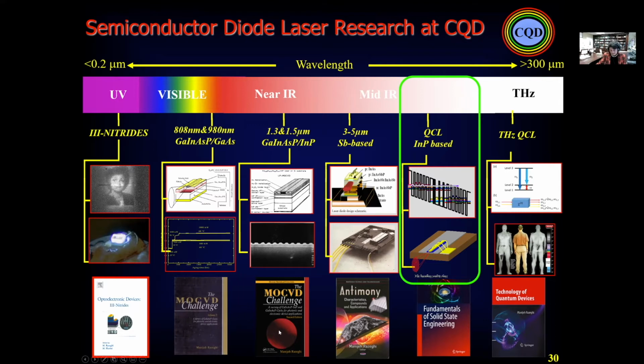You have to know that this picture, exactly as you can see, is the world's first indium phosphide, gallium indium arsenide superlattice that I did. So all of the two-dimensional electron gas, two-dimensional hole gas, quantum structures are based on that, and at the same time, all of the results that I'm going to show you for the quantum cascade laser, or for the detector, are based on technology that I developed at Northwestern.